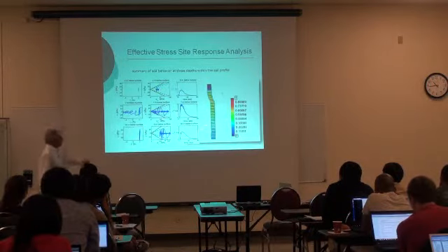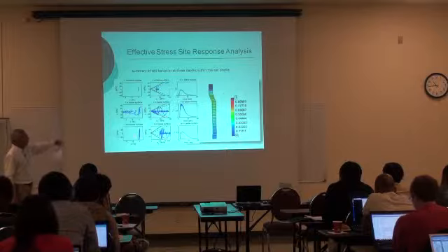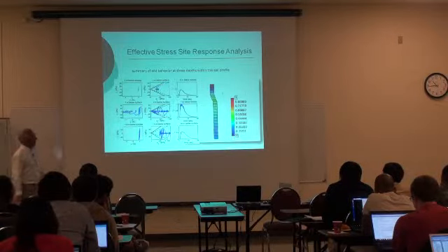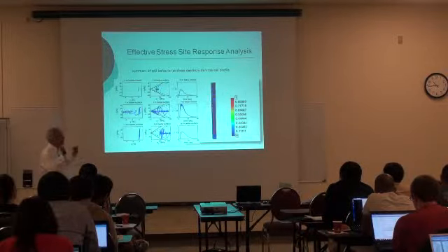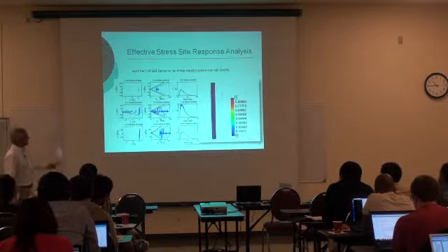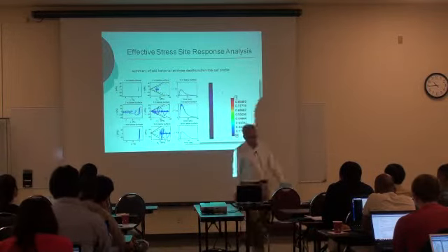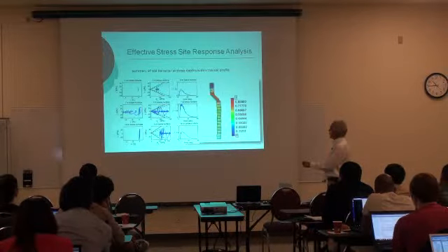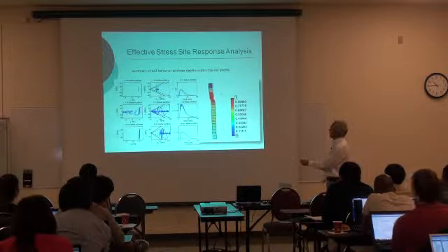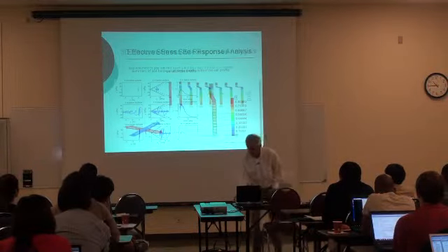And then when you are at the bottom down here, the shear stresses are larger, but look, the response still seems to be more in the linear elastic regime. Okay, so here what you have is just the deformation and the pore water pressures in the soil. You see generation of high pore water pressures. When they are red, it is liquefaction, so you see large deformations there.